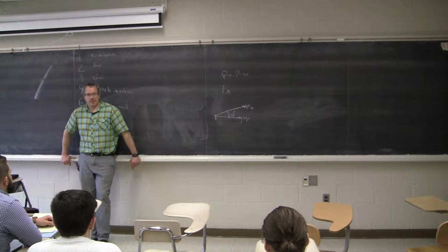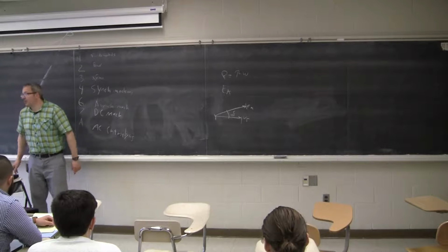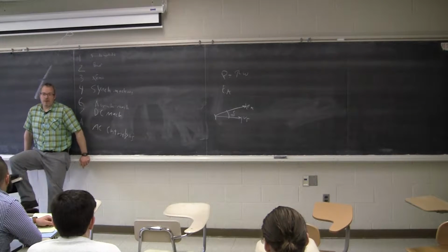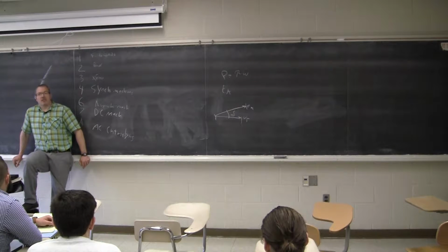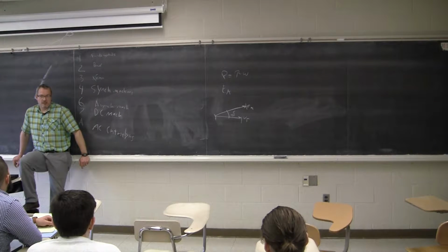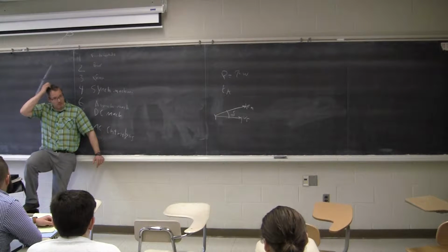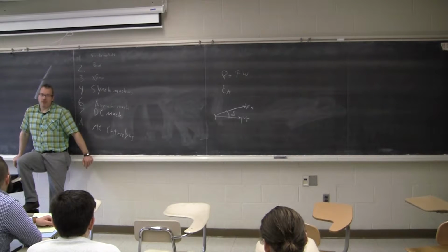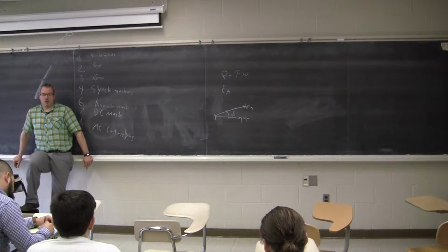And then with three-phase, do we need 3? Do we need the square root of 3? A hint: the only time you really need to worry about square root of 3s or 3s is when you're dealing with phasors. If you've got a voltage phasor in there, you have to be mindful of whether you need 3 or square root of 3. If it's an impedance, it's always 3 if you're trying to go from single phase to 3-phase. We live in a balanced world in this class, so everything is 3.